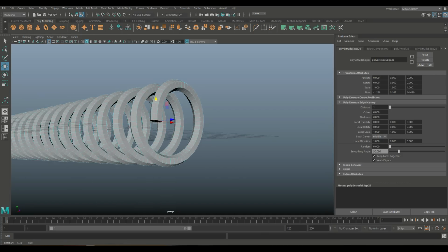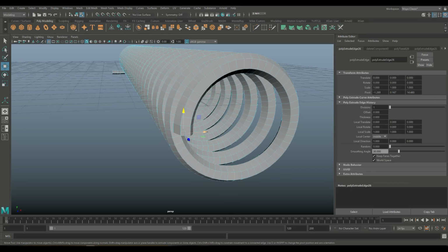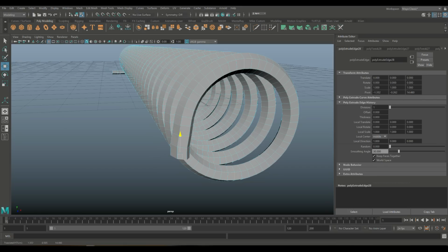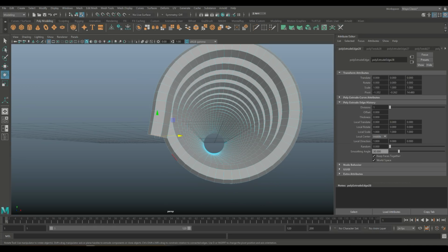And again, many ways to do this. One thing you could do is create a curve and kind of extend that. We're not going to do that. G to repeat, W to push down. And we're going to slightly start to rotate that like this. G to repeat, push down, move forward. And this is kind of finicky because you need to be somewhat precise with that. G to repeat and W to pull out. And again, rotate that a little bit.